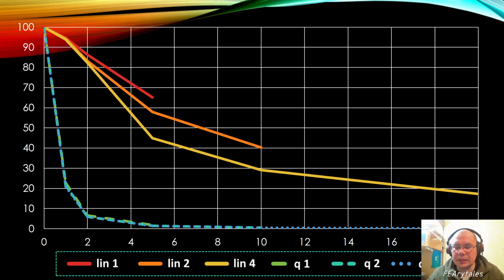The reason is that linear tetra is more stable for obtaining a solution. Yep, you need a much finer mesh and you need a lot of resources to calculate it, but it's more stable. So use linear tetra in this type of task.